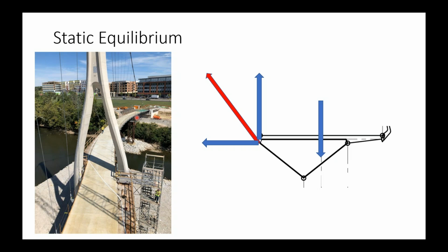So we've got cables connected to the left side of the deck on the near span and the right side on the far span. With these cables connected to one edge of the deck and inclined outward, we know that we've got a horizontal component of this cable force, which is carried by the deck as if it was an arch in plan view. So we've got arching action of the deck to handle this horizontal component of the load.